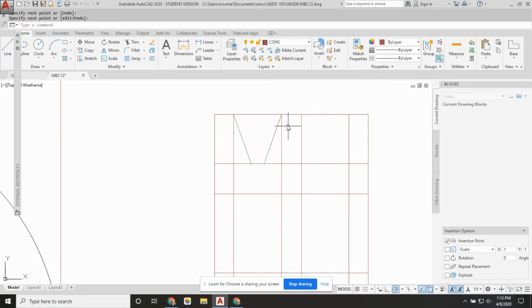And that's another way to look at it, because we know the location or the start point of the angle at the top. We know this should be 40 degrees when it's done. So that means we know that from 270 degrees, which this line is going down 270, I can just calculate 20 degrees from that line in this direction and this direction. So then again, if we trim everything, we have the pulley feature showing up properly in that view.